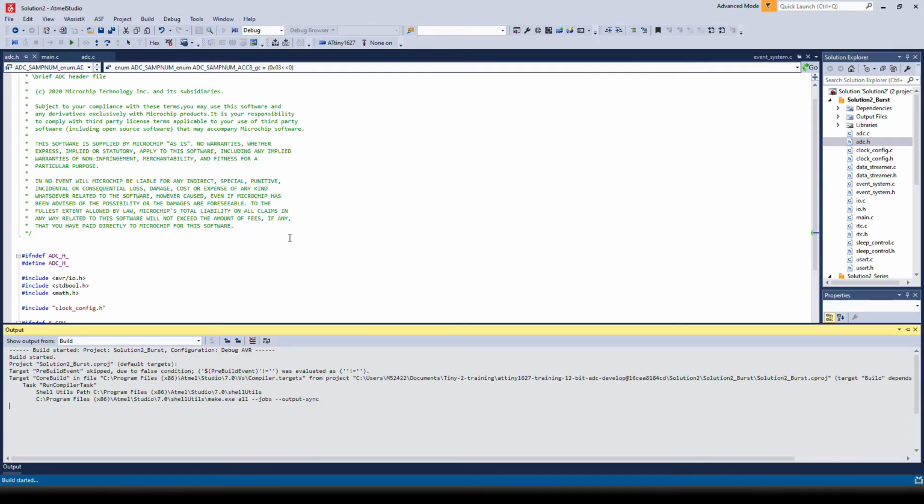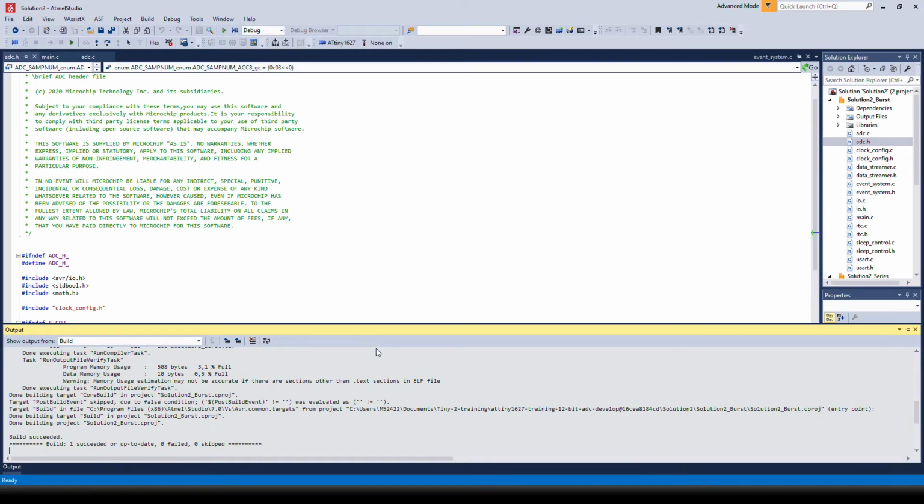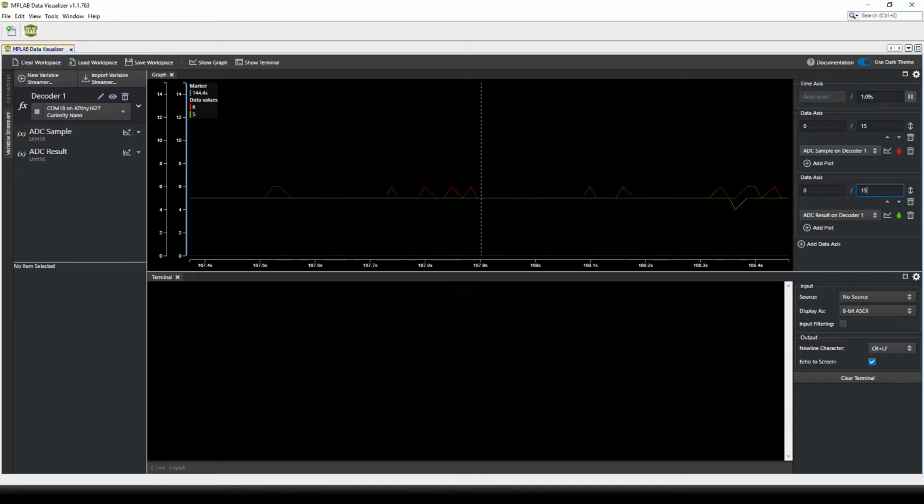We flash the device. And if you now look, we see that sometimes we get these spikes. We are not able to average out as much of the noise this time because we're using fewer samples. So the conclusion is basically that the more samples you have, the better your ability to suppress noise, the more of the noise you can average out.